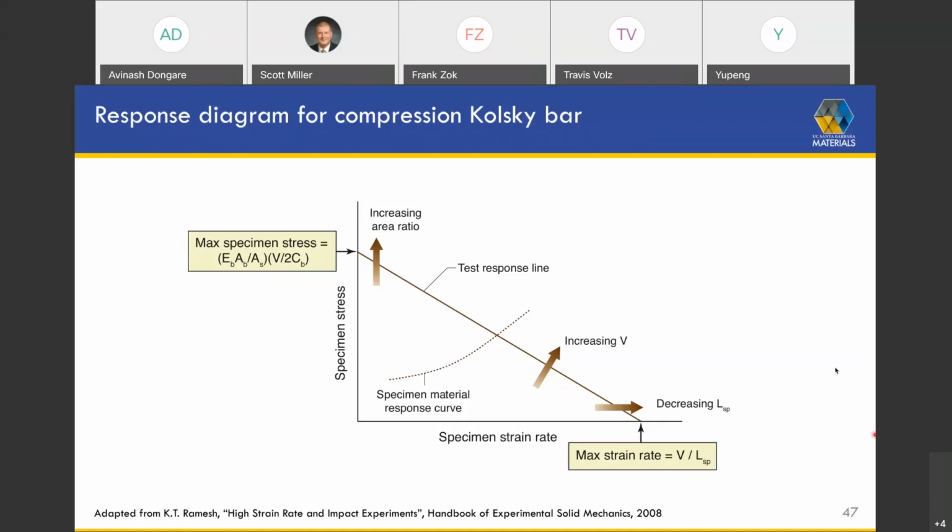Now, we assume that we know the cross-sectional area of the sample to begin with. And you're spot on when you say that the area of that specimen will change as it's deforming plastically. Provided the deformation is volume conserving, and in most metal deformation problems that's a very good assumption, then you can use volume conservation in combination with information about the axial strain on the specimen to compute the instantaneous cross-sectional area.